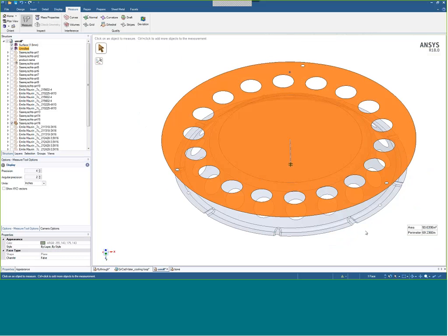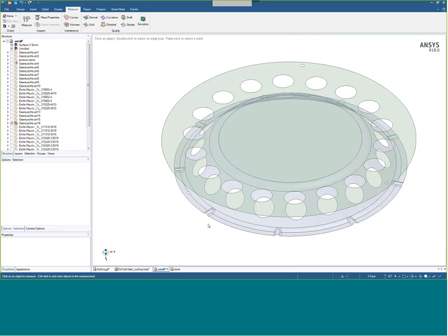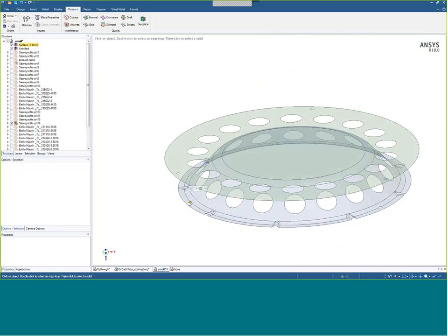So we're trying to keep the area, and we're also trying to keep the edge lengths as close as possible to limit the stretch that's going to occur. And all the small details you see in one, you'll notice also appear in the other. And just to be clear, you can't flatten something unless it's wrapped in a very basic surface, what's called primitive surface types, things like cylinders and perhaps things like cones. But when you get a part like this, when it was actually manufactured, it absolutely deforms. So flattening is always going to be a least deformation problem. That's how we tackle it. You will never get exactly the same length because mathematically it's absolutely impossible.